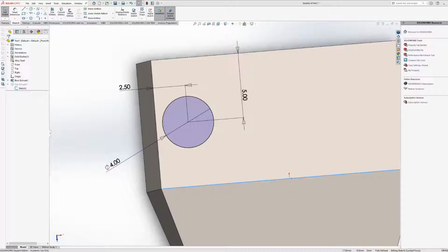So the one thing that I would do in this case is you see that horizontal red bar, correct? If I'm thinking about it correctly, what that's indicating is that the small 0.79 distance on the bottom right is conflicted by saying that it should be both horizontal and vertical.